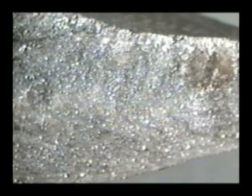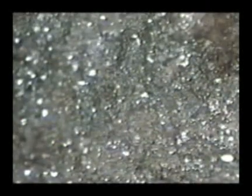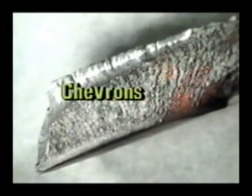This valve head fracture has a rough texture, gray color, and hardly any plastic deformation. It also sparkles with different lighting angles, all characteristics of cleavage fracture. In softer metals, a surface feature called chevrons may develop. These are ridges on the fracture which usually spread out as the crack grows.